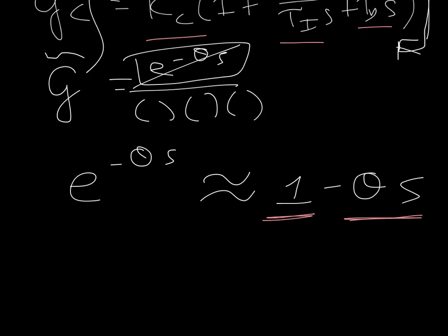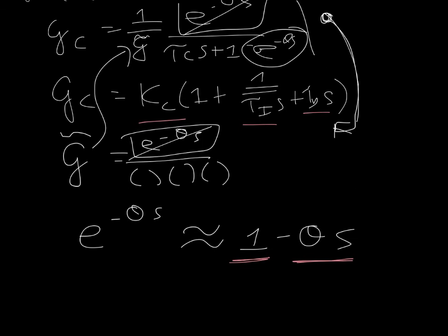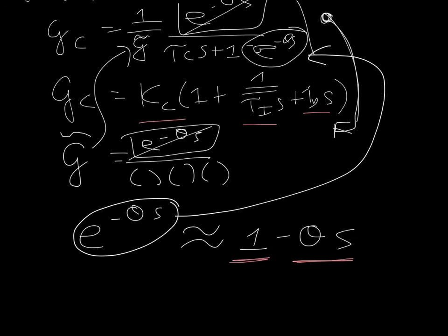And so we'll plug this approximation in there, and by the time we're done, we'll have a purely rational function which is the same order as the PID controller, and we'll then calculate the coefficients by matching coefficients. So we'll calculate these controller parameters by matching coefficients, and you can go onto GitHub and see how I've done that using SymPy.